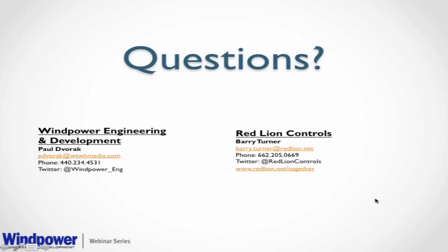That timeout could take a few seconds before you actually get a page can't be displayed. But in a control type network, you want that to happen immediately. So if the PLC or the drive were to stop communicating with whatever device it was communicating with, you need to know it right away. And so Ethernet IP, for example, was built on top of Ethernet to add that deterministic nature to it.